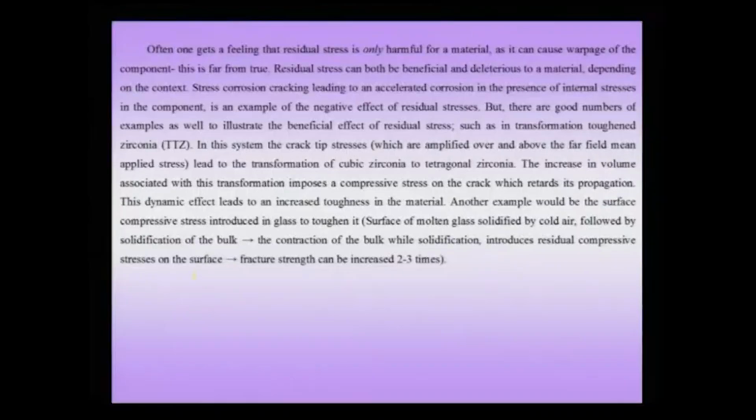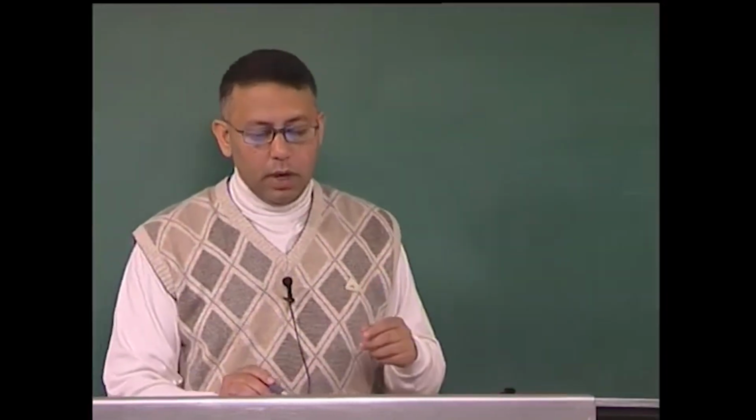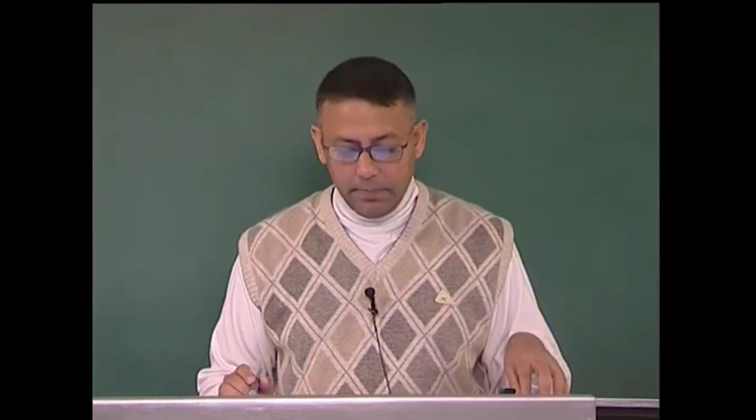So, let us talk about stress corrosion cracking, which is an accelerated form of corrosion in the presence of internal stresses in the material or the component. In this case, clearly residual stresses are bad, because that is what is giving rise to stress corrosion cracking, and in the absence of stresses this will be normal corrosion, which will have a much lower negative impact on the material.